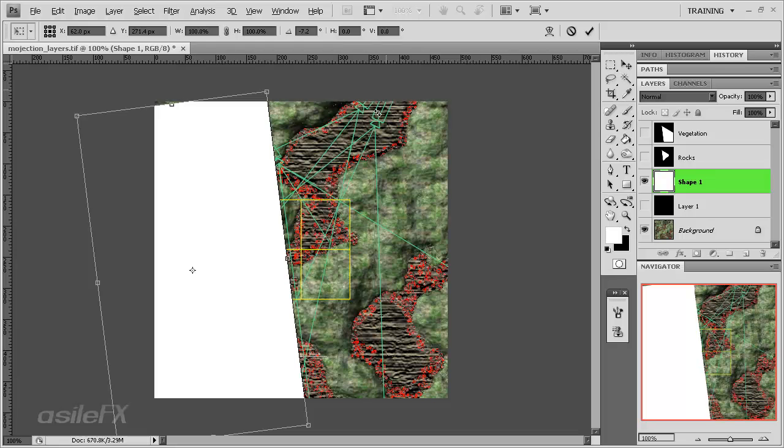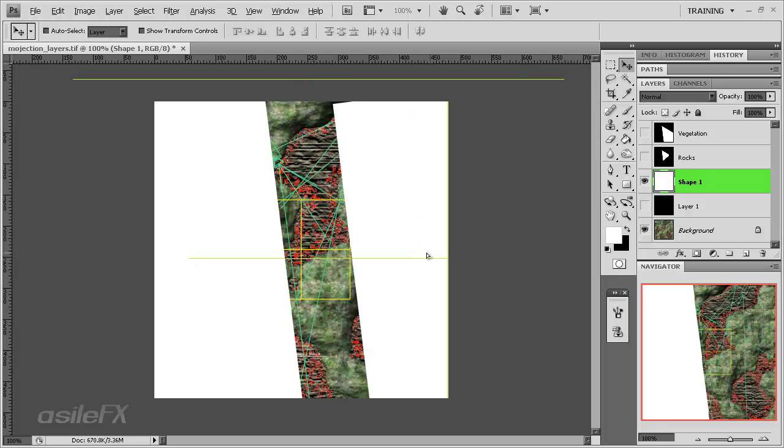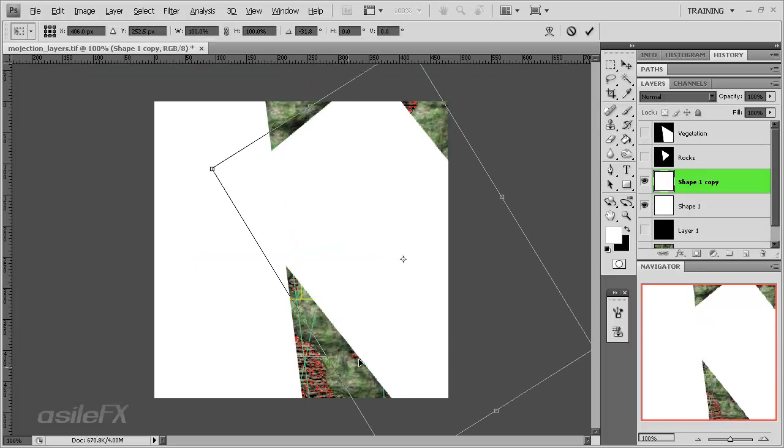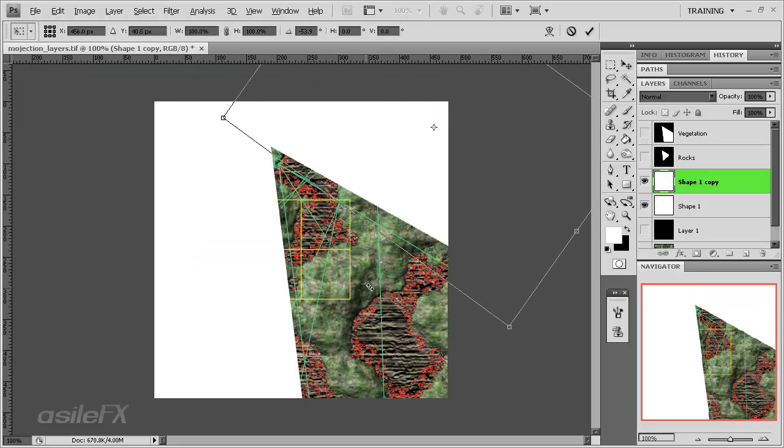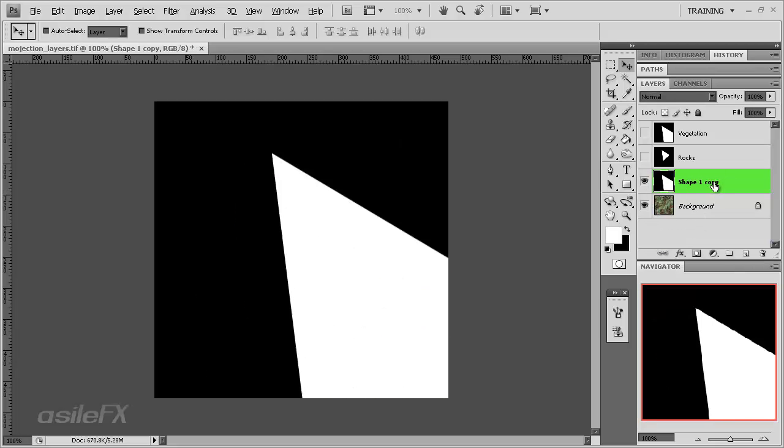And I do have the other camera showing in this version. Just drag it a little bit outside the bounds, and then holding down Alt and Shift and using the Move tool, which is V on the keyboard, you can create a duplicate, then Control T to free transform, and I just went ahead and fit that in, and then turned on that background. Selected all the layers, Control E to merge them together. Then we can invert it to get the correct alpha output.